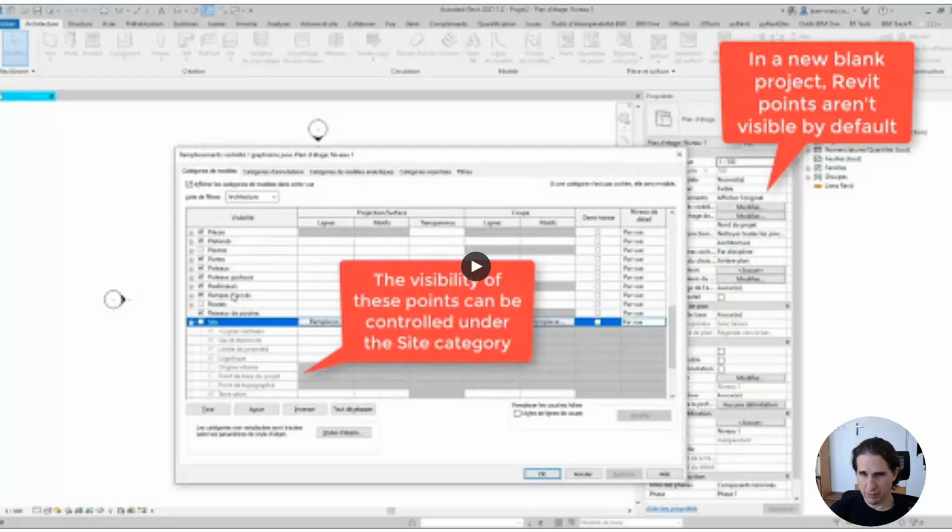So just a quick note on that. If you specify the coordinates, that leaves the point in place, but moves the Earth and project included so that the point displays the correct coordinates. Specifying the coordinates is not the same as entering the coordinates directly in the point, which simply moves the point on Earth.